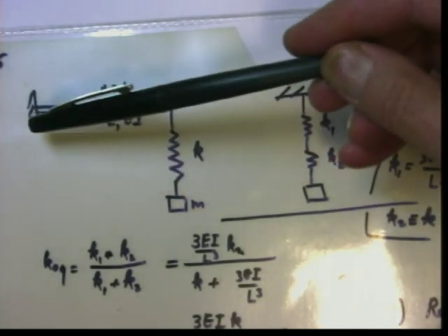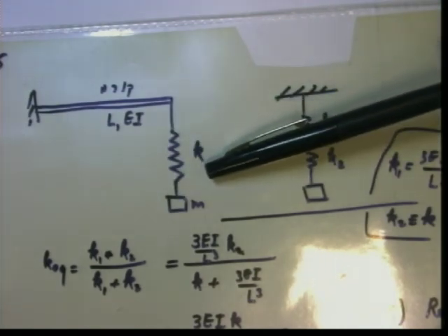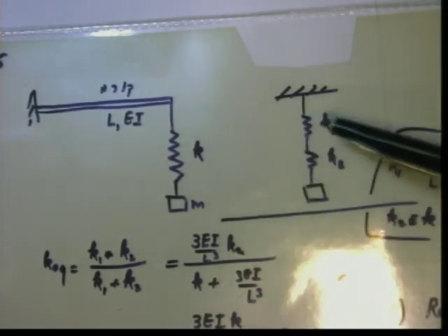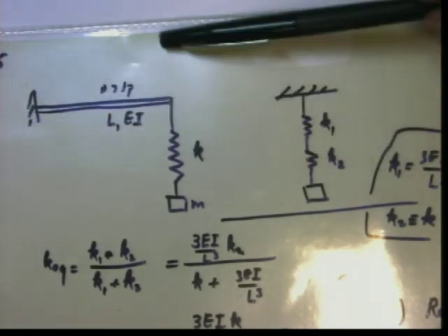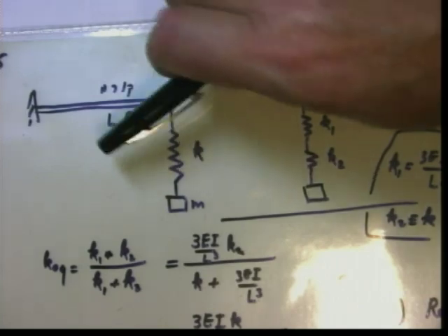So there is this beam and a mass that is hanging on this spring, whose constant is K. Now, this is actually springs in series, because this guy is a spring. And we said that this tip is vibrating in this direction. So this whole thing is a spring in this direction, because this point moves in the transverse direction. So this mass is able to move in the vertical direction only.